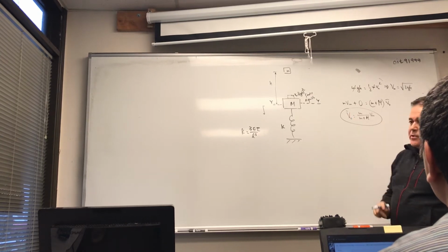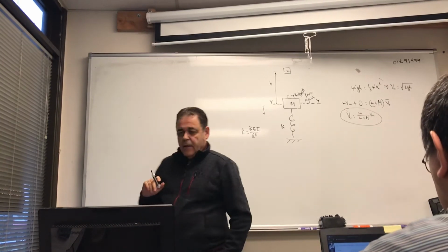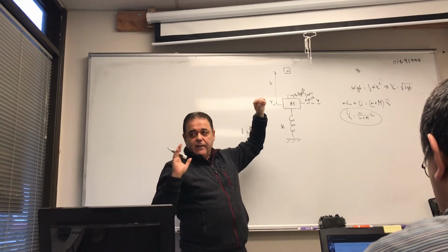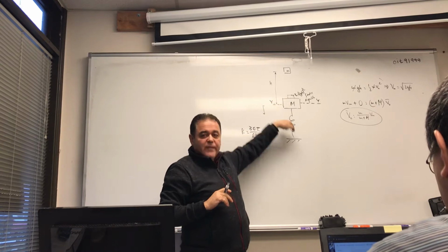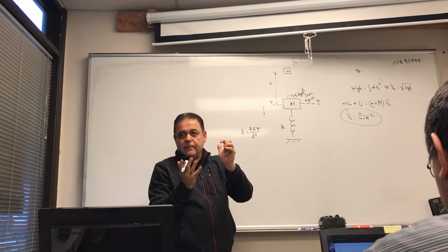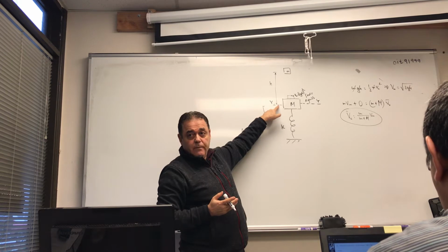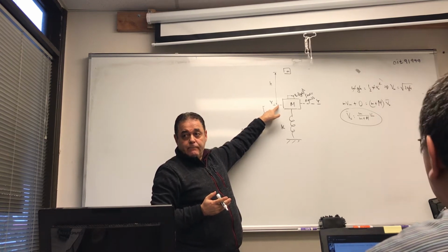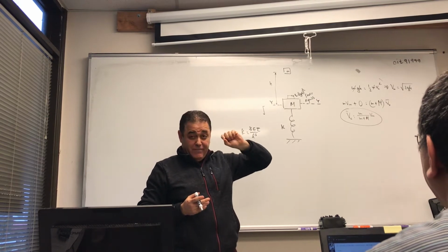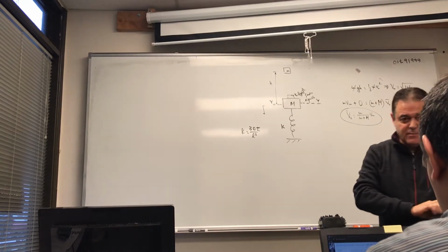Now, another interesting thing that you have to worry about when you do these types of problems is, qualitatively, this thing is going to move down. It's going to be just another bigger mass on top of a spring, and you're going to be vibrating. Are you going to be vibrating about this position? No, there will be a new equilibrium position. Remember, a vibrating system always vibrates about a new equilibrium state, okay?